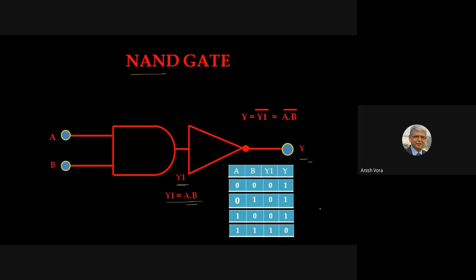You will not get all the graphs at once, but you can revise this afterwards and then one by one it will be very clear. But the characteristic of the NAND gate, that from the truth table we can see that when both the inputs are simultaneously at high level, we have low output. In all other conditions we have high output.